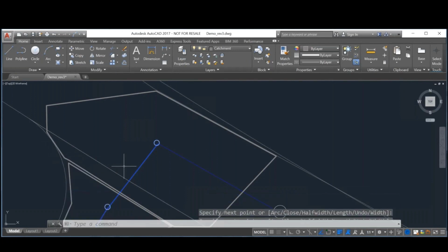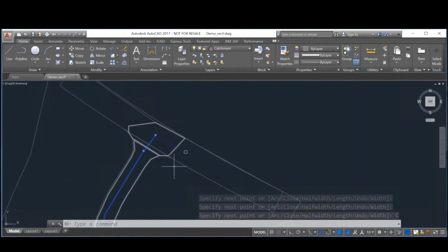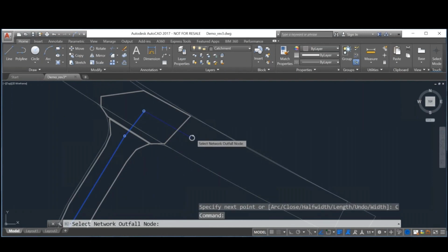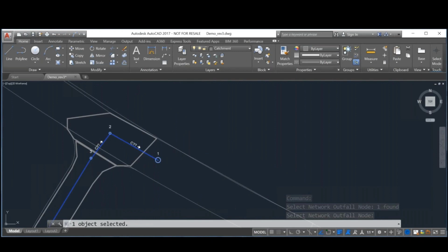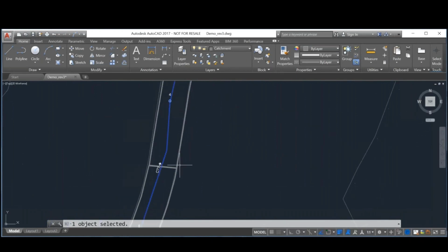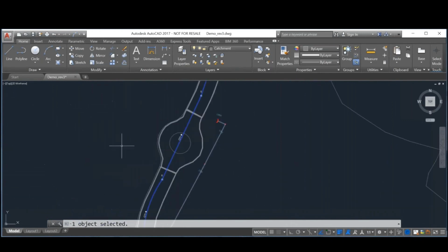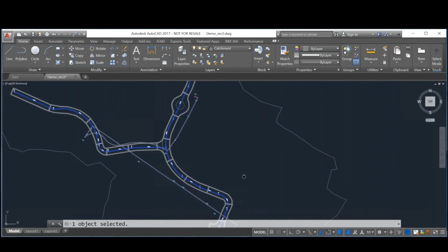So now that we have the drawing complete, we will ask SmartDrainage to convert our drawing of polylines and circles to recognize them as links and nodes that can be read by Flow. In order to do that, by using SmartDrainage, we can auto build the Flow network with a click on the outfall of the node. So here you can now see that the pipe names have been put in, and also you can see that there's some curved pipes that have also been recognized as links.